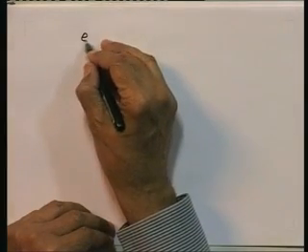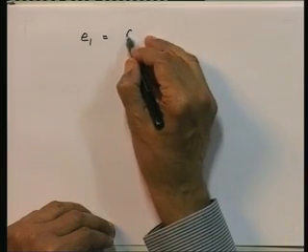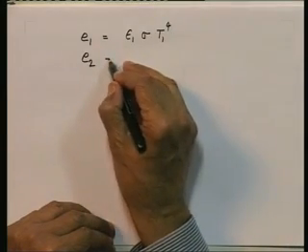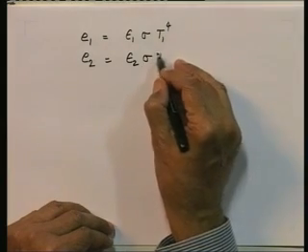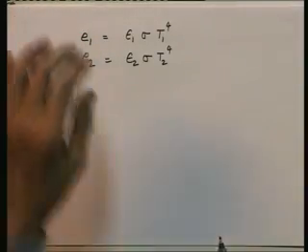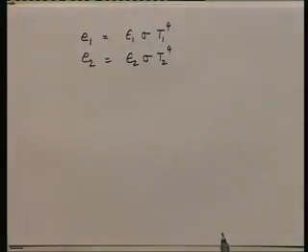Okay. Now, let us do the following. In order to derive this expression, let us consider the radiation going back and forth between these two infinite surfaces. Before I do that, let me first of all state, from the Stefan-Boltzmann law, the emissive power of surface 1 is epsilon 1 sigma T1 to the power 4, and the emissive power of surface 2 is epsilon 2 sigma T2 to the power of 4. Okay. So, I will keep on writing E1 and E2 for some time. Right at the end, I will substitute these expressions for E1 and E2.